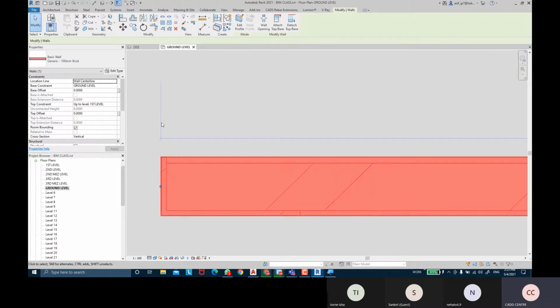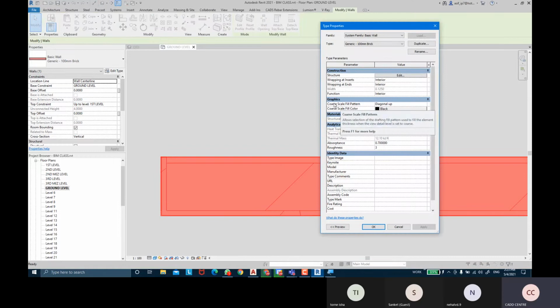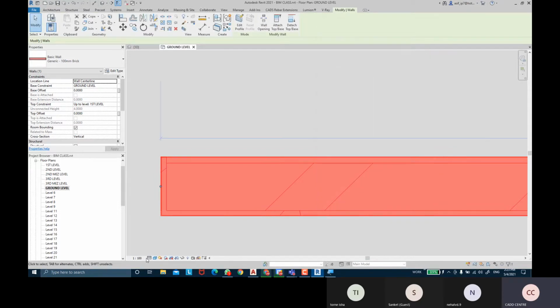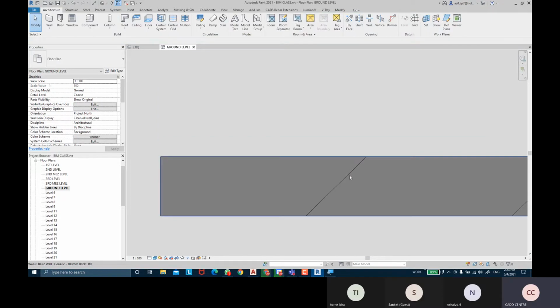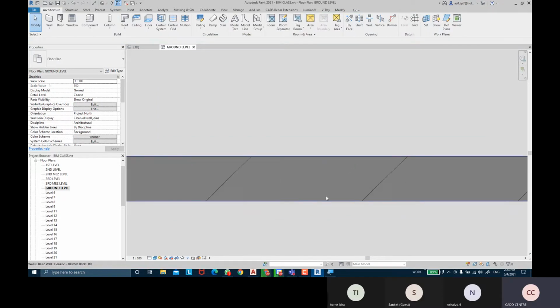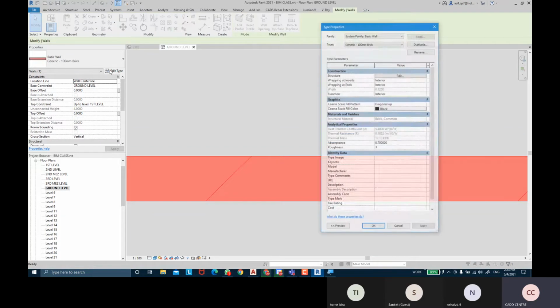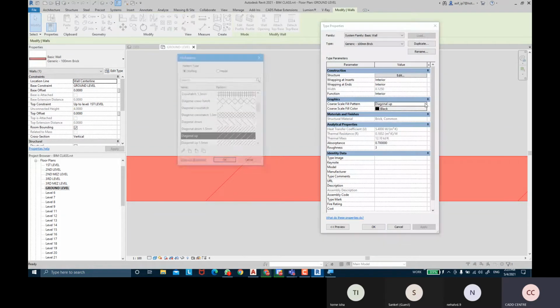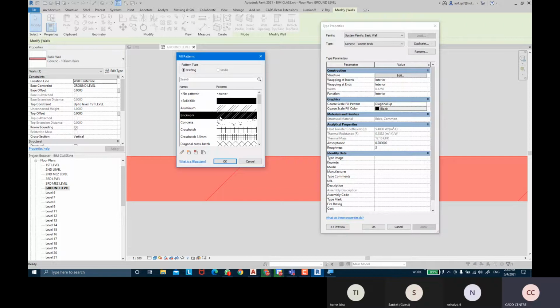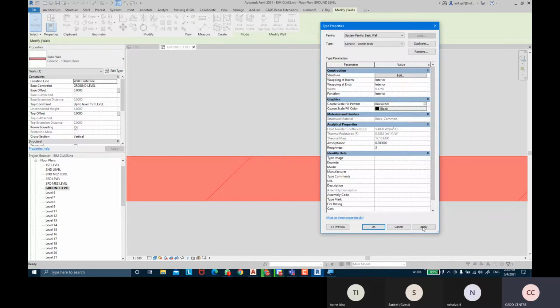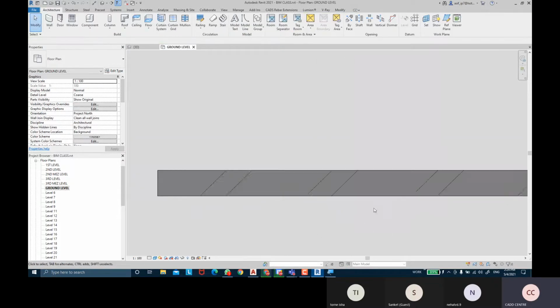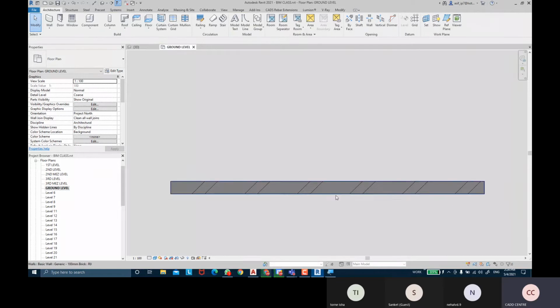Now if I select this wall and come into the edit type, it says over here coarse scale fill pattern basically. So which means, if I kept the detail level at coarse, which hatch pattern should show here basically. Supposing it's all bricks, so I'm going to tell it that instead of diagonal up, I'm going to pick a pattern of brickwork, and click on OK. And if I click on apply and now I click on OK, now it will show me that pattern of brickwork, just the brickwork pattern, not the detailings of the plasters or the paint at all.